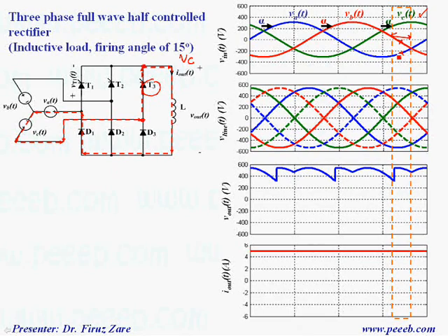And over that cycle here we can see that still phase A is lower than phase B and phase C. So this diode conducts. That means this terminal, which is phase A, is connected to this terminal. So here we have this line voltage, which is basically VCA.